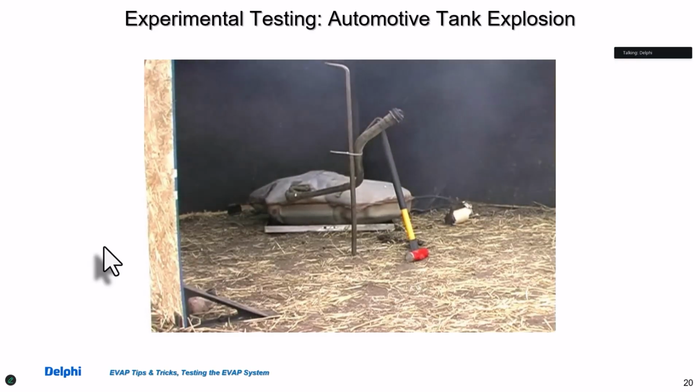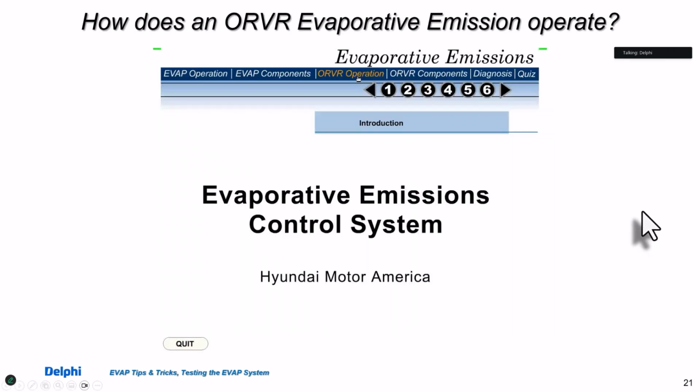Okay, so just a reminder before we proceed that safety should be an issue with EVAP. Don't take anything for granted. You are working with fuel, air, and possible spark. So common sense goes a long ways.